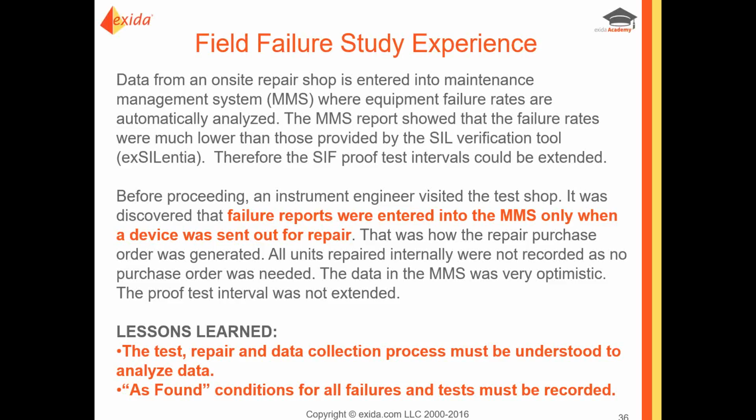However, one of the instrument engineers visited the test shop and discovered that failure reports were only entered into the management system when a device was sent out for repair. And that's because you had to enter it in order to get a purchase order. If they could fix it in the shop, they didn't need a purchase order, and they did not take time to bother entering the data into the failure system.